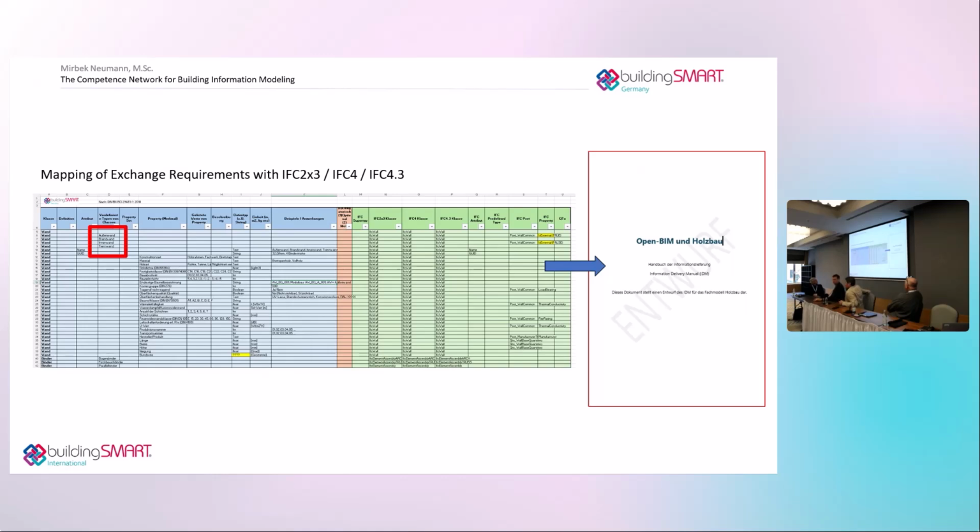external, internal walls. Not many know that external or internal wall in IFC is actually just a property. If you check the IFC class or entity IfcWall, you'll go to a property set called Pset_WallCommon. You will find, wow, there is a property called IsExternal, and that's a Boolean, so it means true or false.